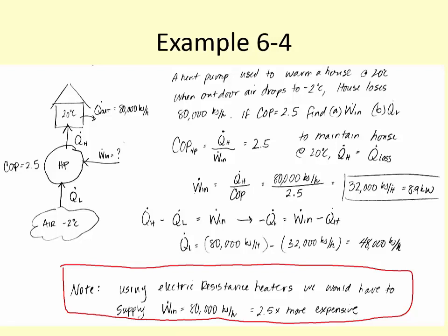Because on a heat pump that can do both, the evaporator and the condenser switch roles. So one will get hot, one will get cold, and then that's how it defrosts itself. So if you ever have ice building up on your heat pump and it's not defrosting itself, you can flip it to heat pump mode in heat terms, or vice versa, depending on what season it is. Same with your car. If your car is freezing up because you're running the air conditioner too much, you can switch it to being the heater for a while and it will thaw everything out, and then you can switch it back.